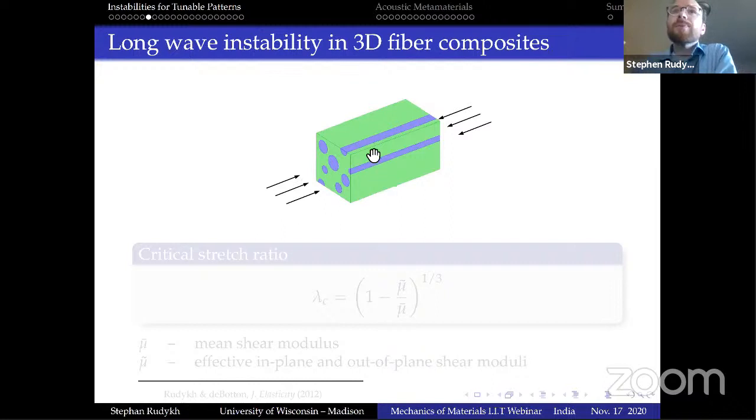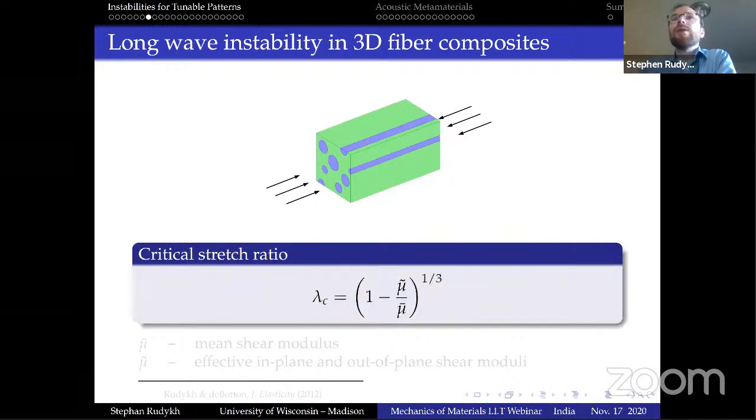And now it appears that if we obtain the nonlinear effective behavior of this material, the energy functions and the stress-strain relations, then we can use the machinery of that loss of ellipticity analysis that I mentioned for the macroscopic instability, and then we can derive a compact formula based on this effective energy function that was derived from the micromechanics based approach.